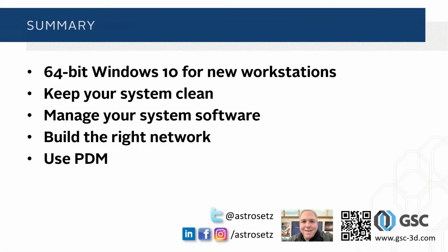So, kind of a summary: keep your system clean, manage your software. Don't just be putting things on it that you don't need, because everything's going to take away from SOLIDWORKS performance. And if you're sharing files, I would say use PDM. And again, we can even talk about another future thing. You can have someone do a presentation on 3D Experience. I can't imagine anything that's going to let you share files globally but work locally, which is going to be your fastest performance in terms of network hardware.